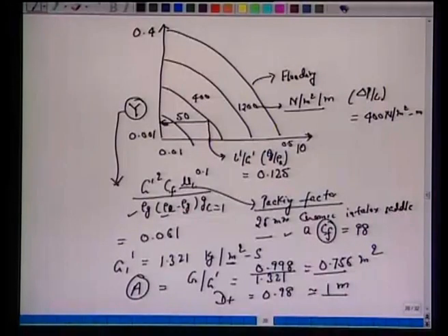And very often, if you recall, we said that we operate at 70%. Most of the absorption columns operate at 70% of the flooding limit. So once you know that flow rate, take 70% of this, and get your new del P by L, the pressure drop per unit length here. In this case, of course, this was given as 400 Newton per meter square per meter. So the problems can be rephrased.